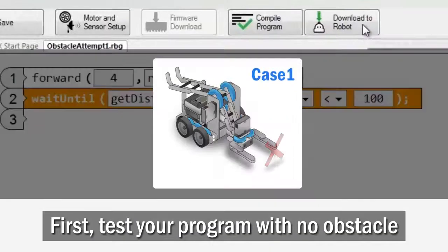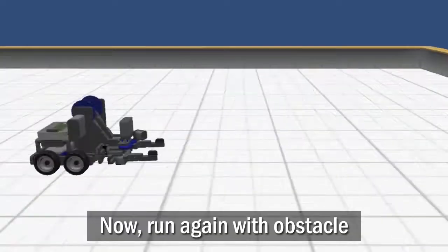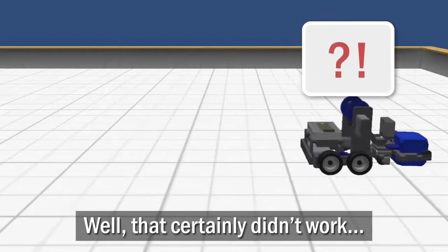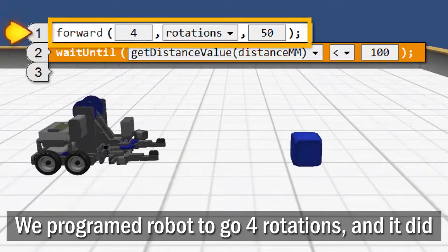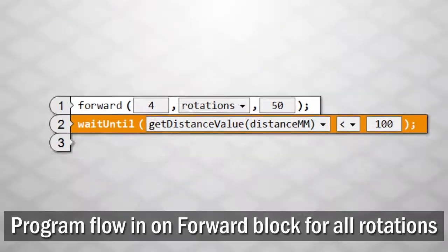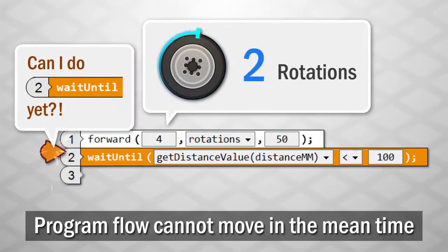Run your program with no obstacle in front of it. It goes 4 rotations. Now run your program with an obstacle in front of it. Well, that certainly didn't work. And it shouldn't, if you think about it. In this program, we told the robot to go forward for 4 rotations, and it did. The forward command block had the program's full attention for all 4 of those rotations, leaving it no way to get to any blocks that would even attempt to check the distance sensor.